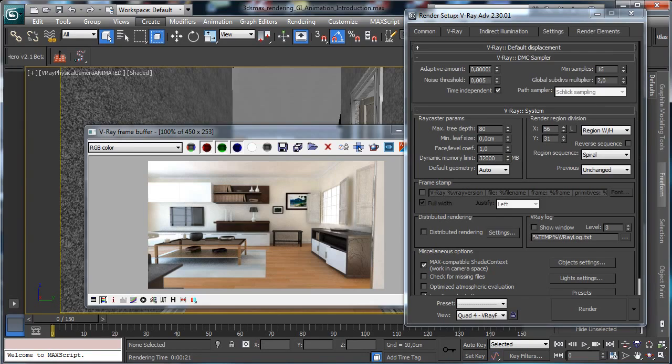So you see, it's really simple to manage fly through, and you have just to play with the light cache and the irradiance technique to save and to process, and we saw also how to optimize the rendering time using just some frames from the complete sequence to speed up the rendering.